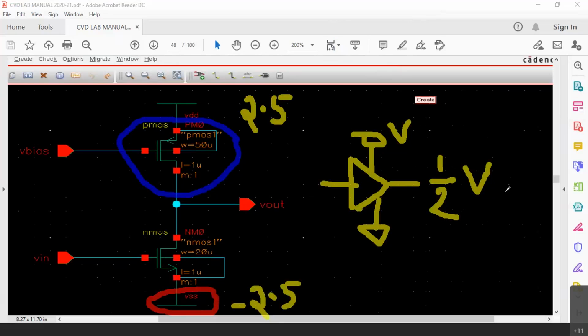That means the switch is supposed to be working at the quiescent point, which is exactly half on and half off. So if you are using an amplifier, you will have to bias this amplifier in such a way that it is at half of the supply voltage. That is why in the BJT circuit, you studied fixed bias, self bias and voltage divider bias. You studied JFET biasing also in the same manner. That was the basic requirement of biasing an amplifier.